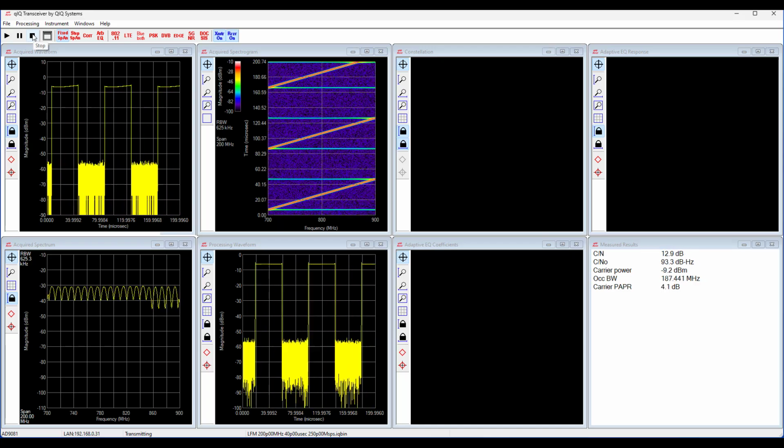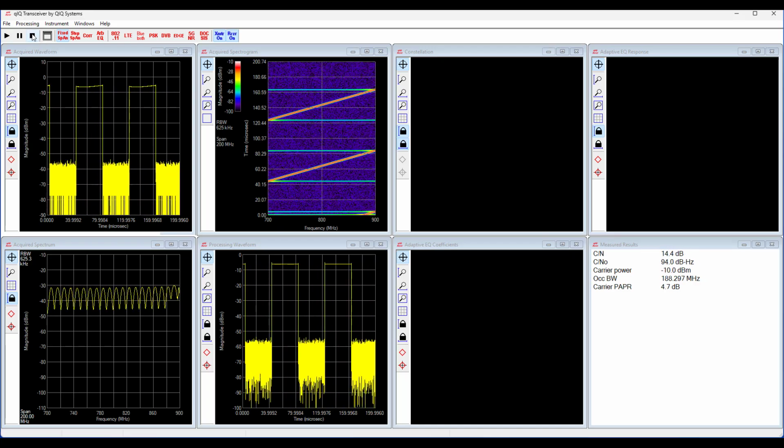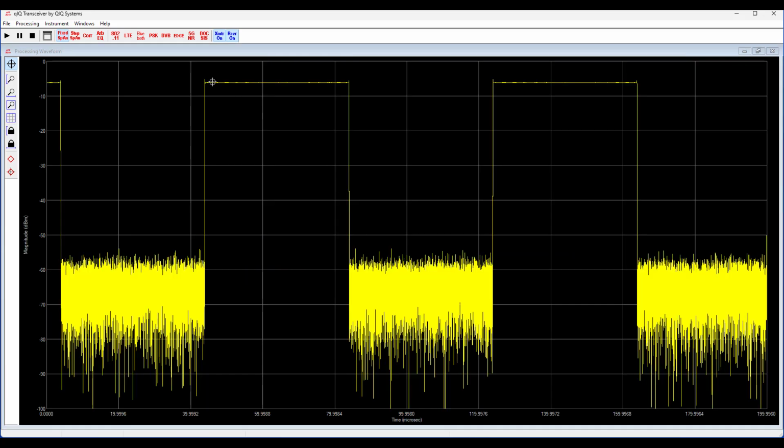All right. Run for a while and then let's stop. And you can see this is the time domain response after we have applied that complex FIR filter to the received data. And one of the things that you can note immediately is that this characteristic of the acquired data, which has this slight droop and then a flip up, has been totally flattened out. There's no droop left in the response up here. We've just flattened out the response.